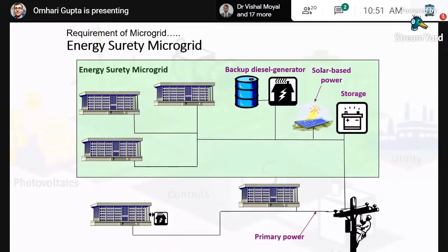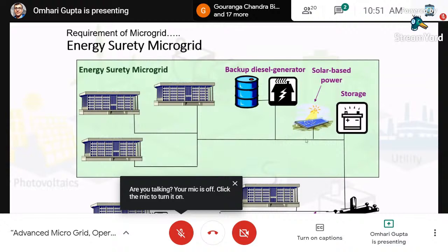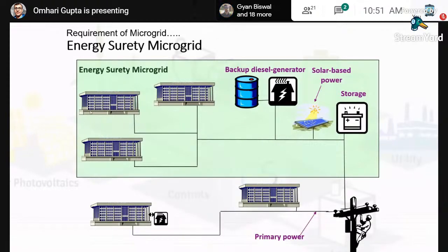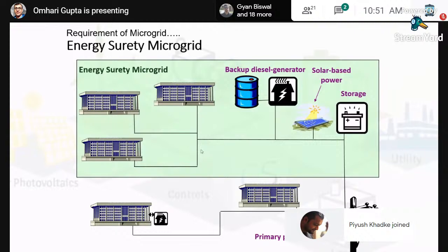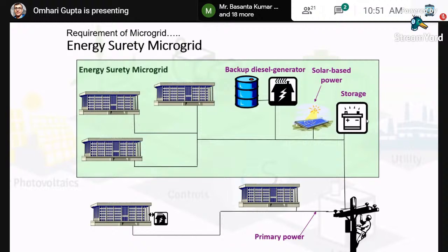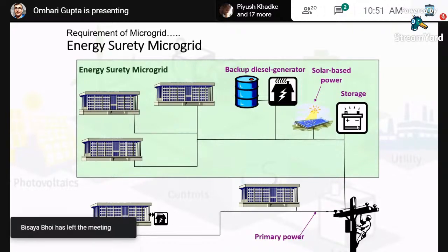Okay. Let's say you have sufficient solar based generation. Then what can you do? You need not start this diesel generator based system, and the load can be supplied through this. Okay. Now, say you require 10 megawatt for supplying these three buildings. If you have 10 megawatt generation, that can easily be supplied without taking current from the storage. If 9 megawatt is generated and your energy storage is able to supply that additional 1 megawatt for several hours, you can use these two to supply your loads.